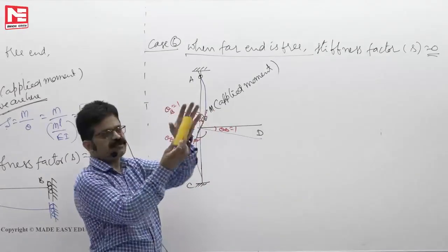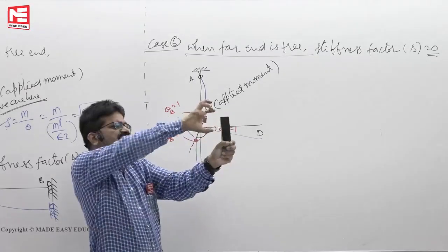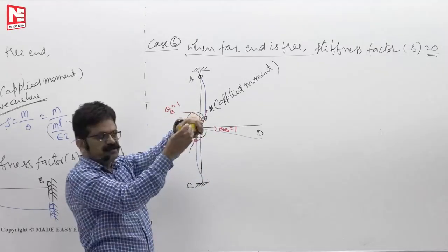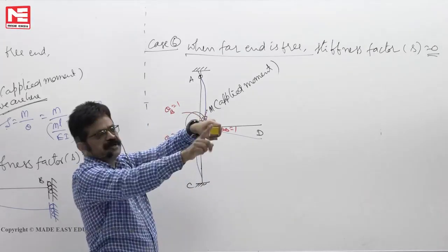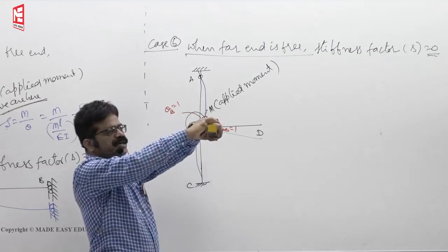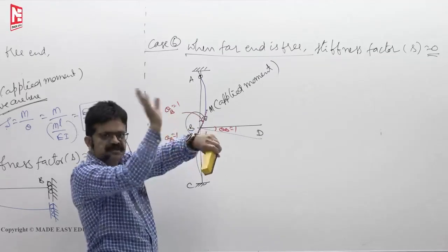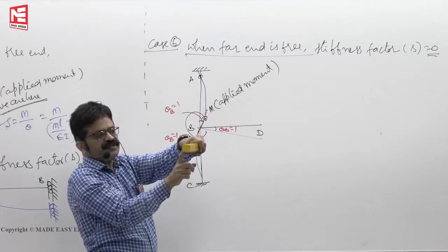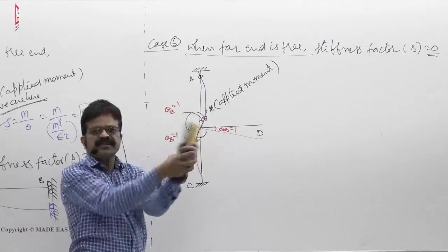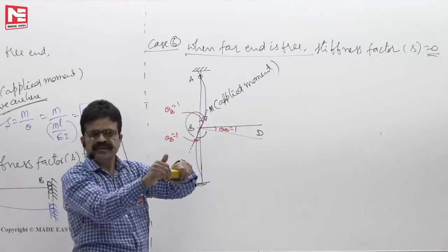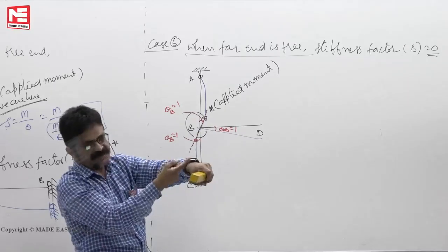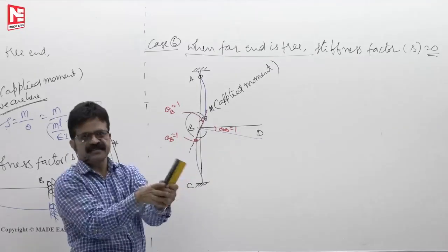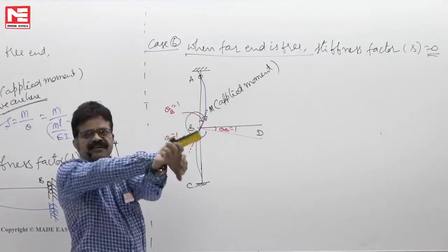It's like this. Supposing that you have a fixed support here, here some hinge is there, then I have to apply some effort, then only it will rotate. Now I don't apply moment here, this is the cantilever beam, this is the support. On the support, I apply a moment like this, suppose the support rotates due to some reason. See, when I am rotating like this, why only one rotation? 180 degrees also I can rotate with 0 moment. But if I hold this one, then if I rotate, you require some effort, then only it will bend and rotate. But if it is free, freely it will rotate like this. If I apply a moment here, freely it will rotate.